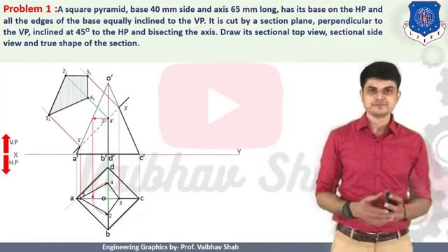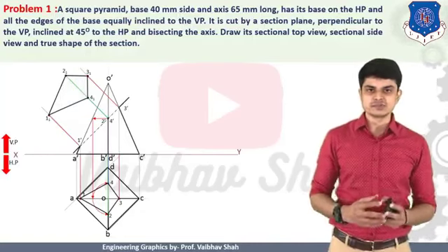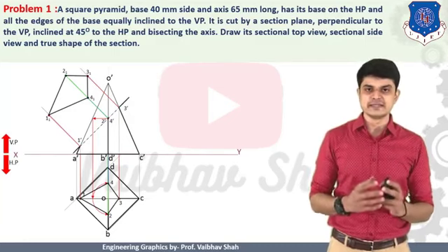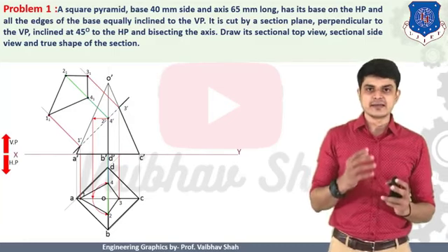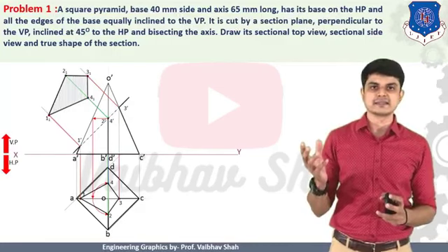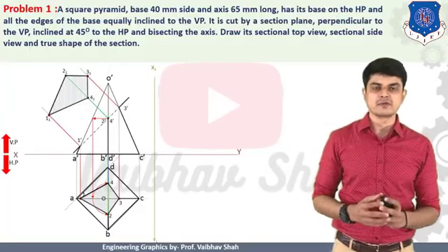Right? Very easy. Now, after getting these views, as these are the section planes, we know that sections are shown by hatching lines at 45 degrees and at equal distance apart. So let us show the hatching lines on the surfaces like this. On this surface as well as our bottom portion. So we'll be having our object generated.